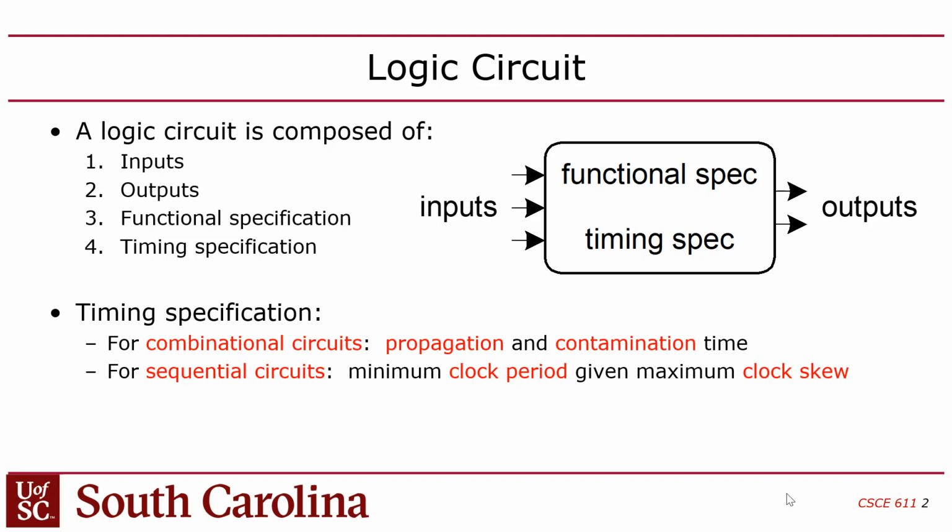And so if you try to not pipeline the CPU, you try to make it a single cycle CPU and do everything in one cycle, you'd probably violate that 20 nanoseconds and the compile would fail, but you might not know why or what's going on, right? Or it would just take a really long time to synthesize because it would have to struggle to meet that requirement. You guys with me? So the timing specification is where you're saying what the clock speed that you want is, essentially, right?